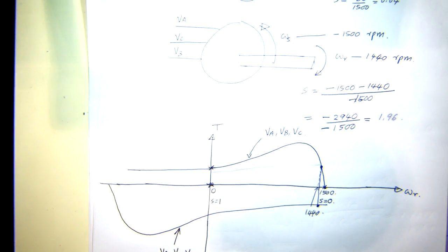At the point of when it's running, it will be conducting some current. Let's say you disconnect it, then it will spark over, I guess. So you need to have some form of high capacity contactor to disconnect it under load conditions. And then you interchange it and then connect it again. And then I don't think you need any resistances.